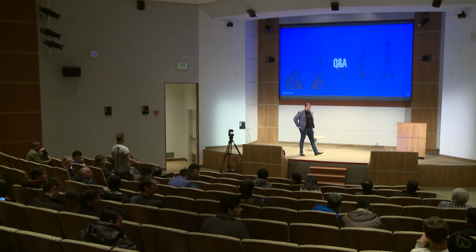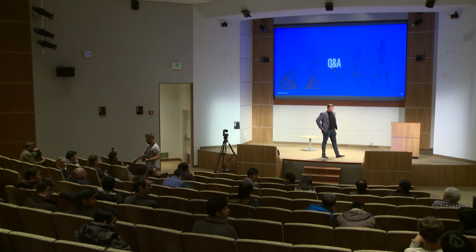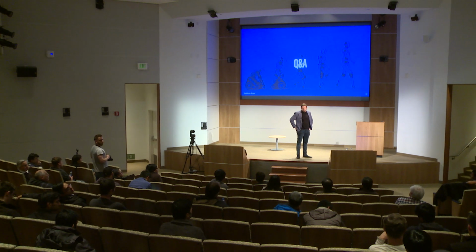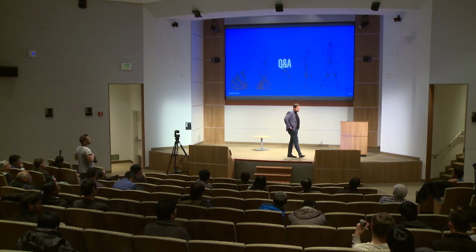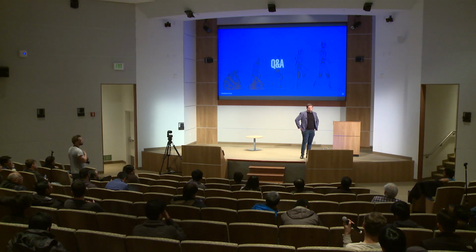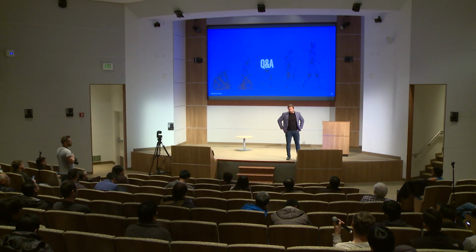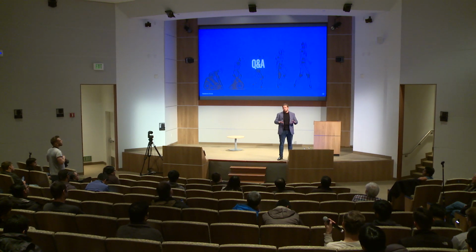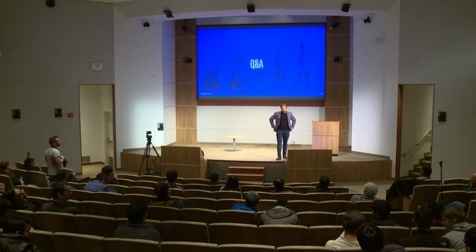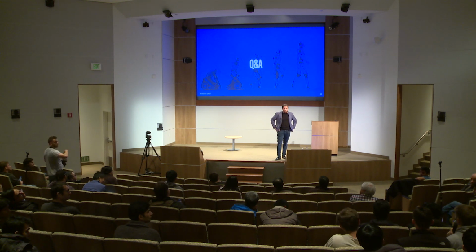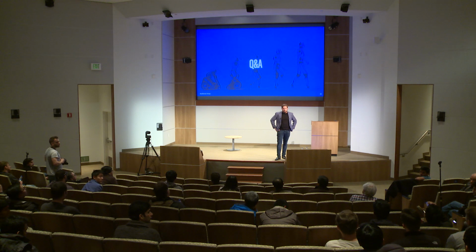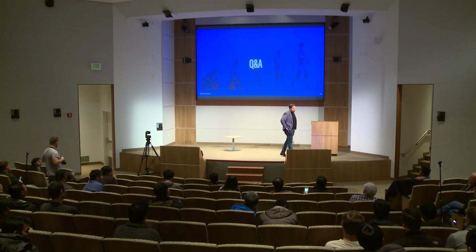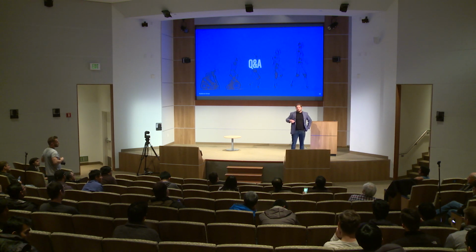On the tracking camera, it seems that most of the data that you're using is coming from the IMU. Can you clarify a little bit about what you're actually doing with the cameras? We're using the images to do, on the one hand, visual tracking, frame to frame. On the other hand, they're an important source for relocalization, which is based on appearance, where we don't make any assumption on geometry. Why are there two cameras? Are you using stereo? Yes, we are using the stereo information, and that is to not have scale drift over time.